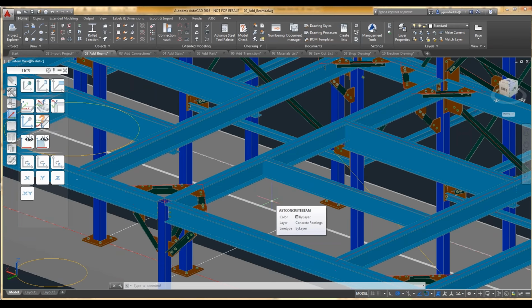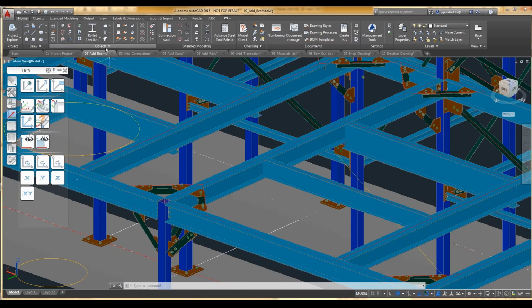Advanced Steel provides a complete catalog of steel sections, including bolts, gratings, and cladding sheets, not just beams. You can take an AutoCAD line and create a smart object out of it, or you can actually draw a beam from point to point. If you wanted to do something like that, we have a command for that as well. So you can pick rolled section, and you just give it a couple points where it starts and where it ends, and then it will create the section.